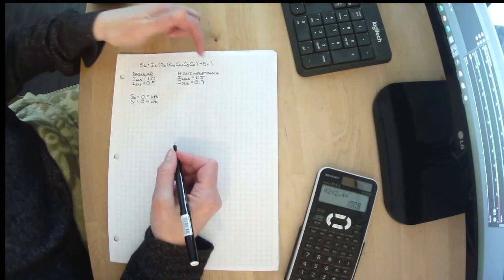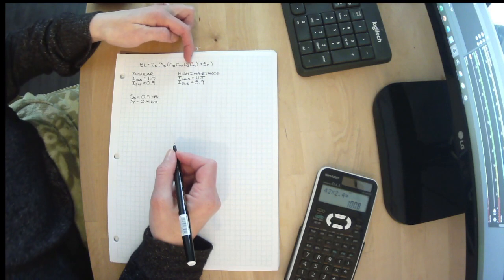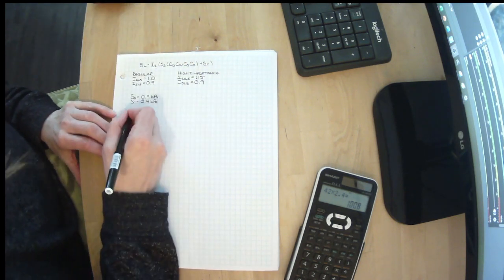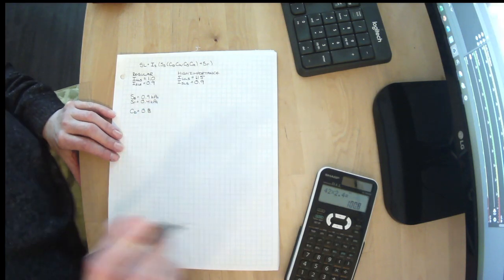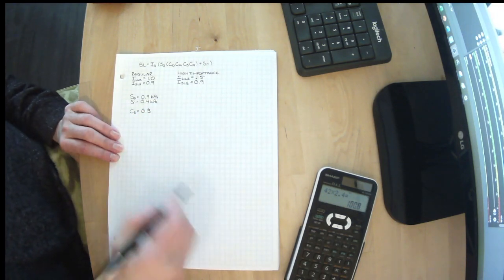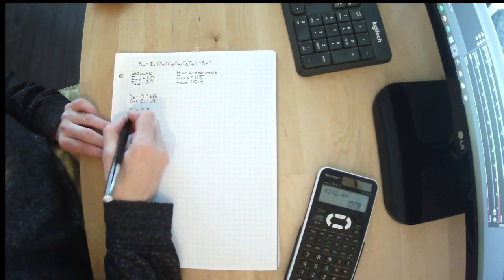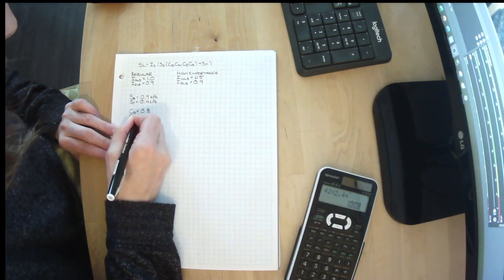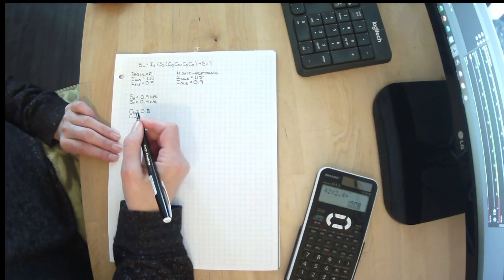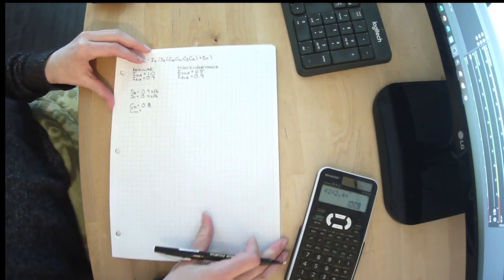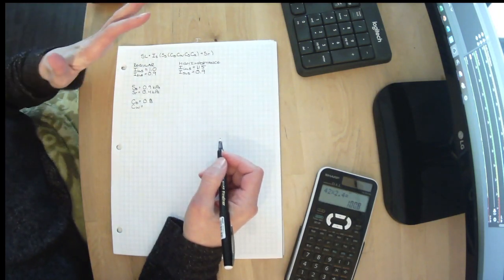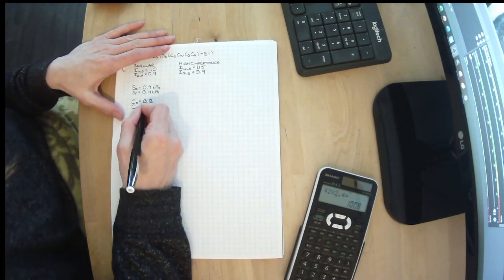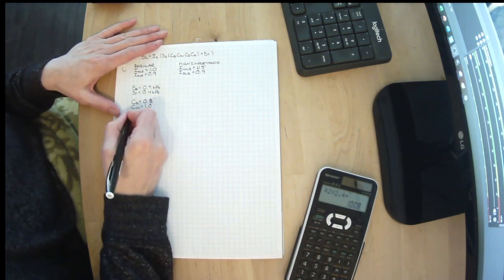So we've got most of our equation. These we know are factors that get applied to it. CB, I've told you you are using 0.8. CW is the wind exposure factor, which you can manage to make something else, but it's really hard, and I have actually never really done it for snow load, so we're going to use 1.